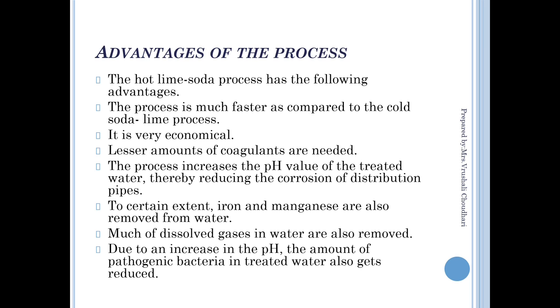What are the advantages of this process? It is faster than the cold soda lime process. It is economical. A lesser amount of coagulant is required. The process increases the pH value of the treated water, as we are adding the soda, sodium carbonate. Due to that, the water becomes alkaline.